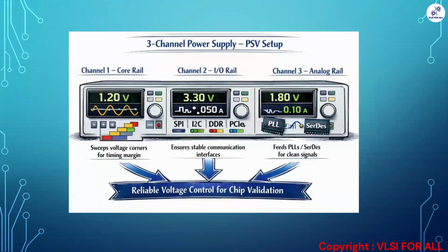In the power supply, we'll be having store and recall measurements, where we can store one particular set of readings, like voltages and how much current. For safeguard, we'll keep the current limit as well as the voltages. We can store and recall those settings. Any doubts as of now?